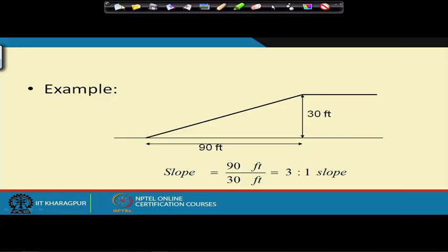Right now the Bhalaswa landfill actually has almost a 1:1 side slope, which is really dangerous. During every rainy season, some of these landfills that we have, I should not call them landfills, they are dump sites, since we are teaching an engineering course here, and from the engineering point of view they are essentially dump sites. Some of these dump sites have a slope almost like this. So it's almost 1:1, and every rainy season I'm really worried about it as a citizen of the country.